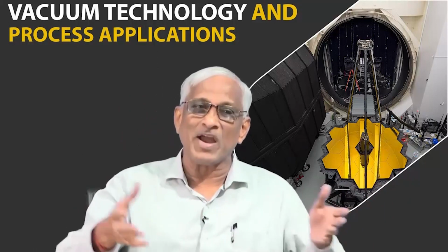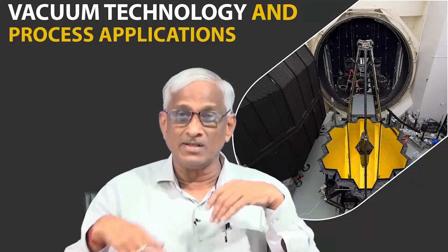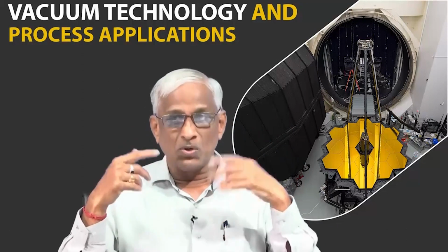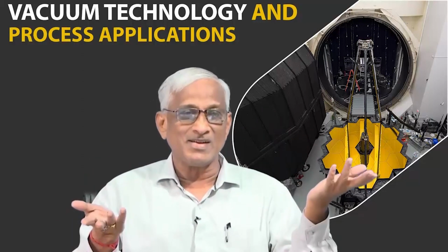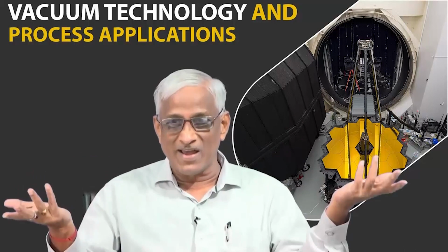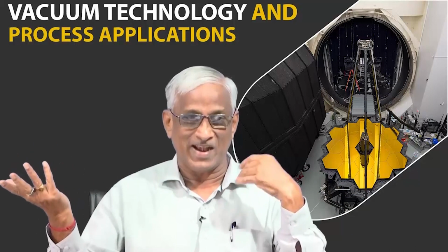So, there is a lot of vacuum chambers and vacuum associated equipment necessary for doing that, along with heat transfer fundamentals and washing with very high quality water, and also trying to control different parameters without any oxygen, because otherwise silicon becomes silicon dioxide. So, the original source may be silicon dioxide like sand.